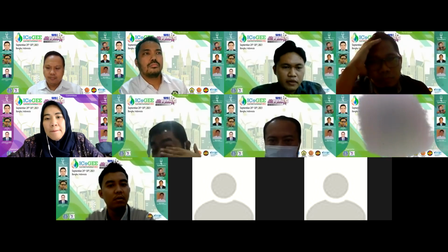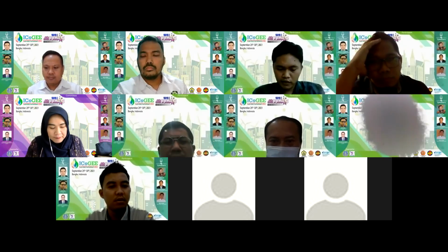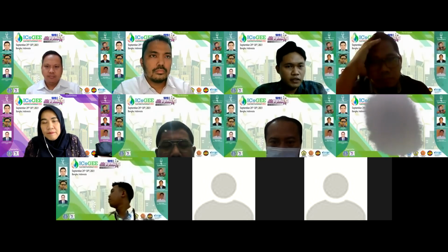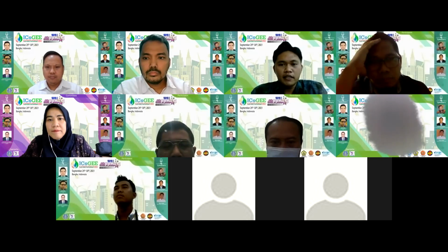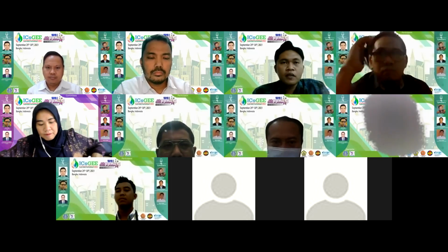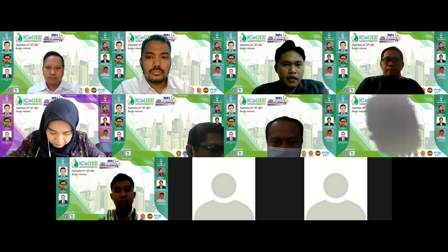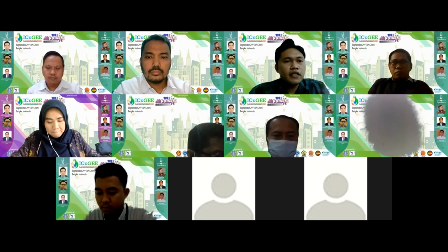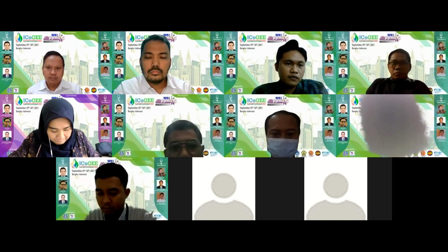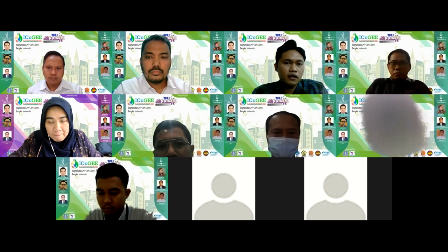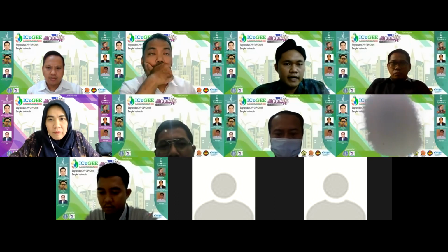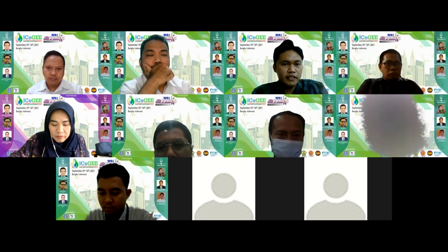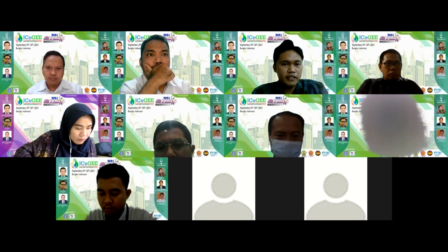Okay, thank you, Mr. Ragil, for the question. Yes, it's true. The main issue of municipal solid waste incinerators is dioxin and furan. But to minimize dioxin and furan, there are several processes that we need to make sure of. First is the combustion of the waste. The combustion of the waste should not be below 800 degrees Celsius inside the grate incinerator or the combustion chamber.